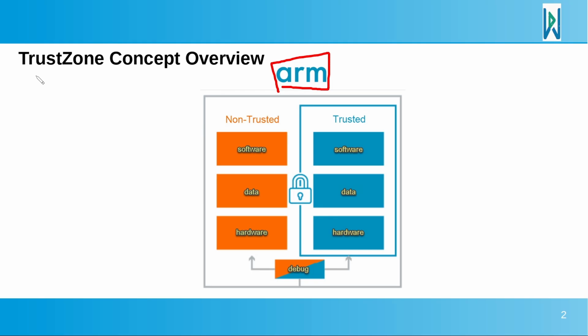The ARM TrustZone consists mainly of splitting our embedded system application between a trusted software entity and a non-trusted one. The trusted software entity will be the software that will have full access to the critical areas within our microcontroller, as well as secret data. And secret data will include, of course, the secret encryption key as an example.